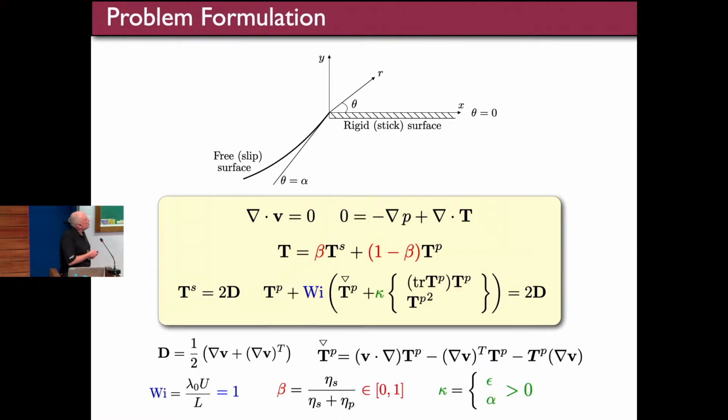For the asymptotics, we're going to look locally at the die lip. So we've got the solid boundary for the channel, and then the emerging free surface. I'll take local coordinates centered at that point, and we'll have polar coordinates, the radial distance r and theta. Theta naught is the upstream wall, the channel wall, and theta alpha is the downstream surface. Technically, theta equals alpha gives the tangent line of the attachment of the free surface to the die, to the channel.